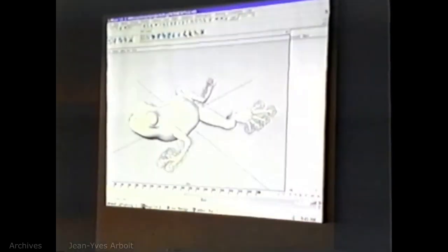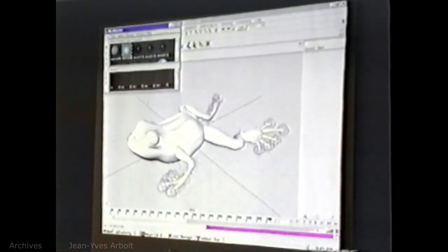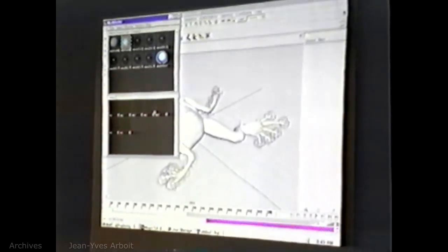Okay, I'm going to open up this file right here. This is the file for prog, and it's missing some textures. So I look inside my multi-lister and I go, hey, what happened? My file textures, they've lost it. The path is wrong. When I double click on the file and it brings up the attribute editor, I look at the path and I see it's looking for C:AW Maya project SIGGRAPH 98 source images. Well, this is not the path.